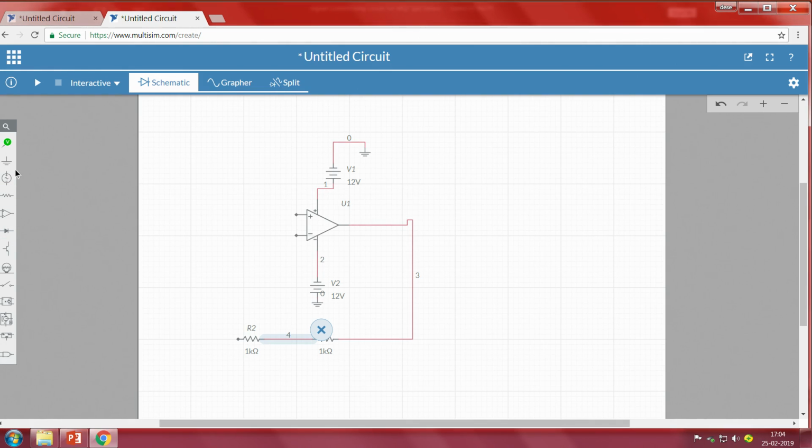And we had given a constant 1.4 volt DC source to the resistor. So this was the 1.4 volts, which was our requirement. That is, when the function generator input goes to 0, ideally I should have a 1.4 volt constant voltage.